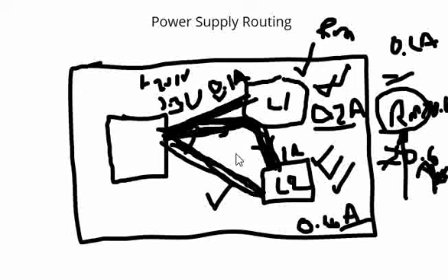So ultimately, it all depends on the load current and the amount of impedance. As the trace width increases, the impedance reduces, right? But ultimately, do we have that much space? Because in the beginning we assumed that this is a two-layer board, so we have components all around. Do we have that much space to be routed? So all these scenarios and discussions come into the picture. Ultimately, the point here is it is safe to do a star routing in such scenarios.